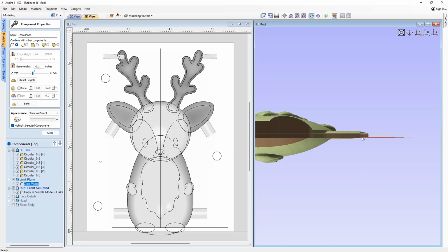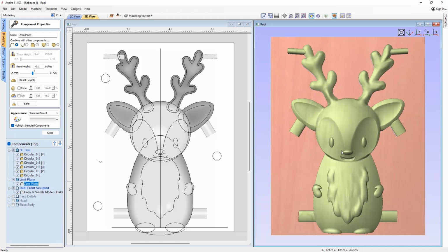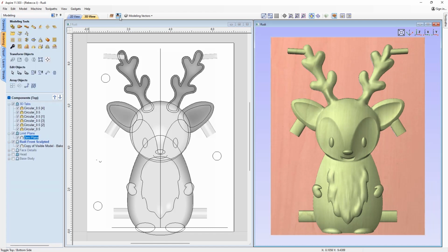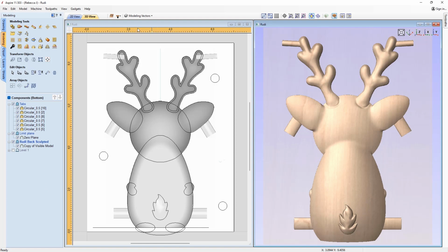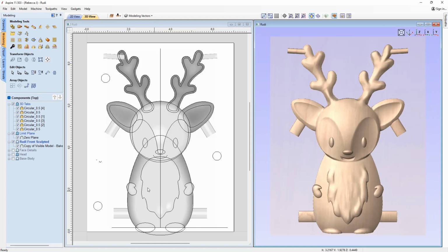And what that will help us do is drop that tool down past the centre line to ensure that we don't have that cusping effect. So that's a good technique to include in your two-sided 3D projects. We've also applied that to the bottom bar just for extra measure. Okay then, so that's pretty much the modelling setup.